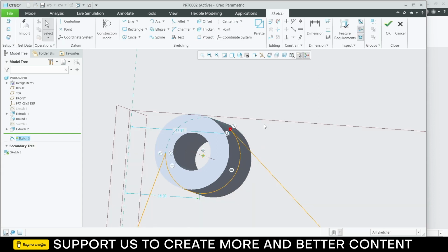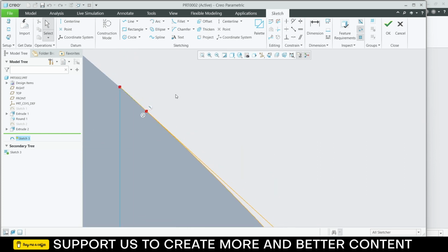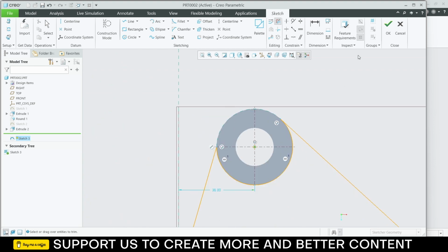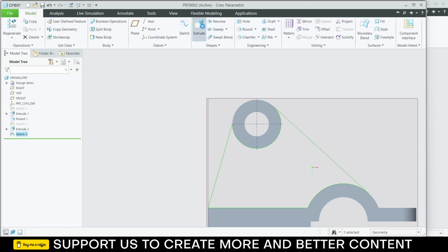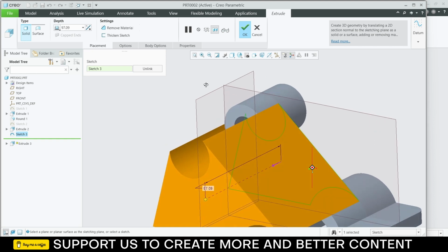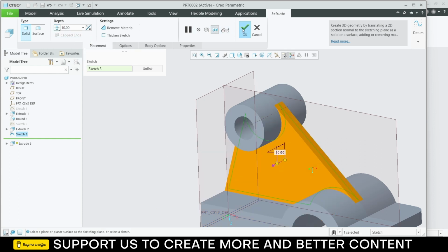Click on edit sketch. So these are 2 points. So just delete these segments, unwanted segments. Click OK. Now let's try the extrude command. Notice it is filled now. So sometimes you have to deal with these kind of weird issues. Just keep a habit of dealing with it. Symmetric. Click OK.